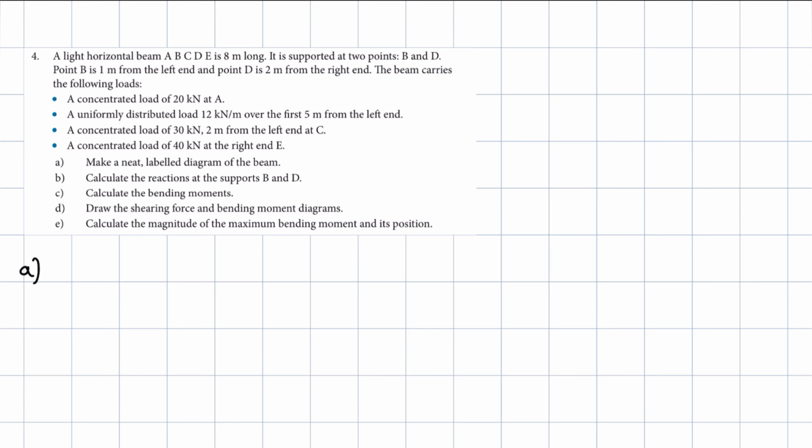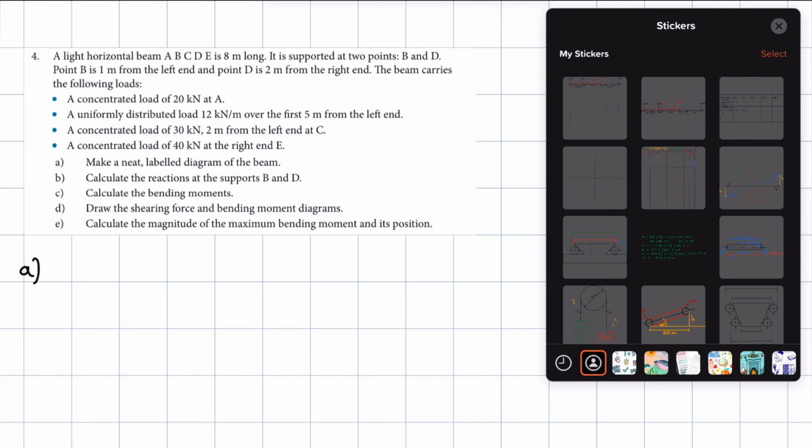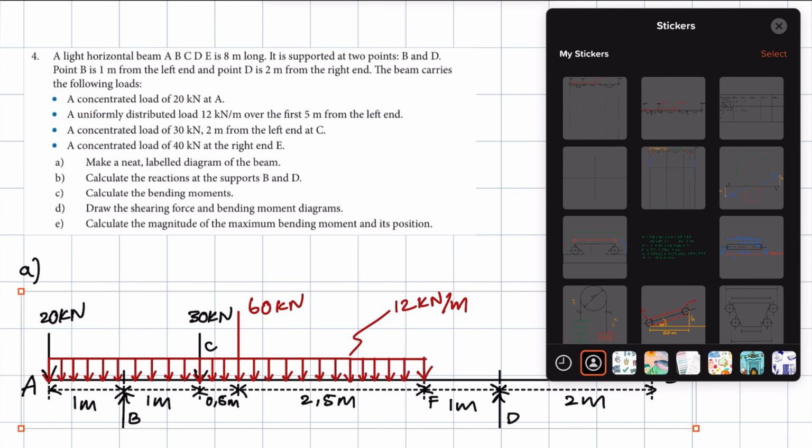Even if they had drawn the beam for you, I always advise students that if you're looking at a problem based on beams, always redraw the beam first so that you can label it in a way that is convenient for doing calculations for the reactions at the supports. For this beam in particular, once you have drawn it, it is supposed to look like this.